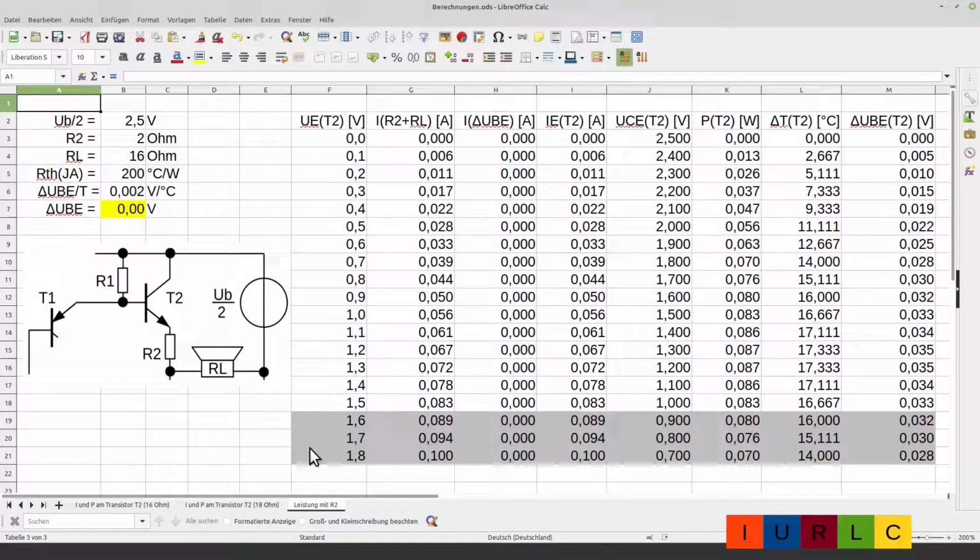This voltage is also our input voltage here. It was our design goal that this voltage is at the same level here. We have here 0.7 volt and here 0.7 volt, and therefore we are here at the same level as on the input. According to superposition principle, we can calculate the current through R2 and the loudspeaker caused by the input signal, and the cross current through R2 caused by the voltage difference of the base-emitter diodes of T1 and T2 separately, and add them later.